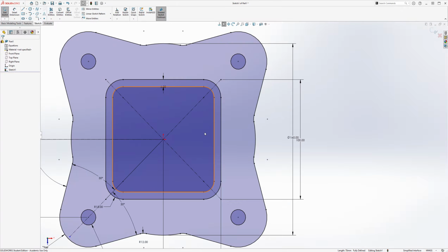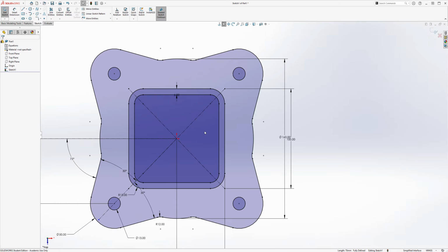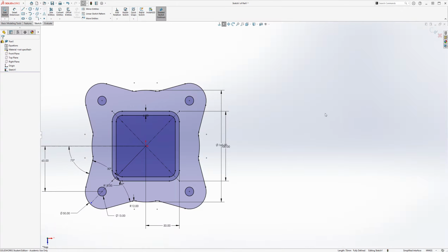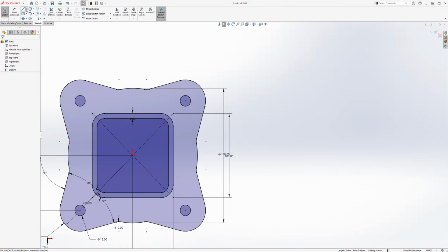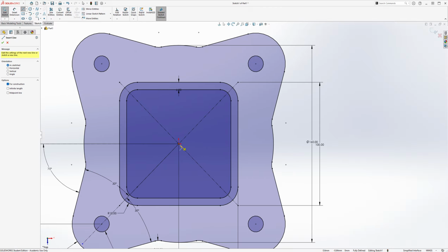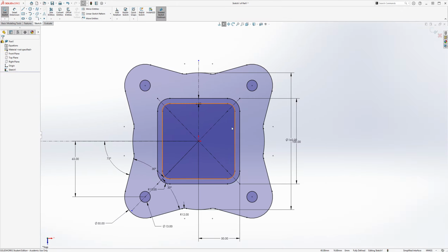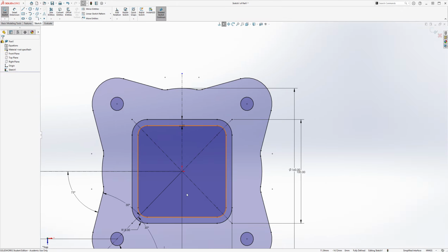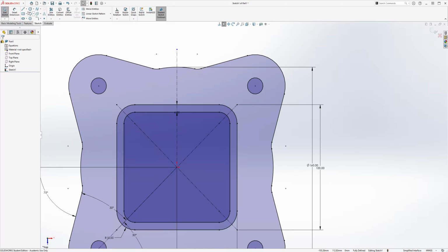And then from here, we're going to add 4 circles. I'm just going to mirror them. So let me just add a vertical center line. I know there's a lot of center lines, so it's getting a little difficult to know which one's which, but bear with me.